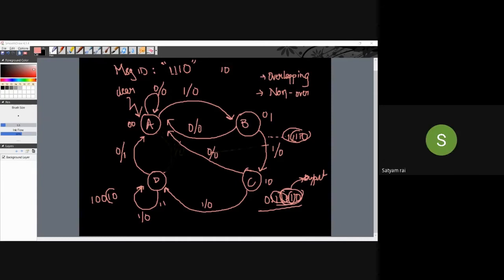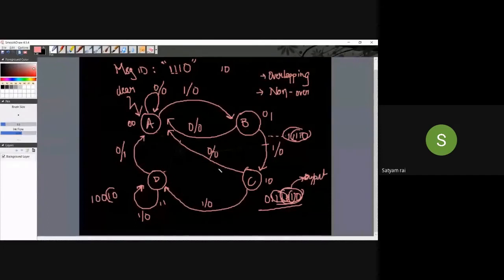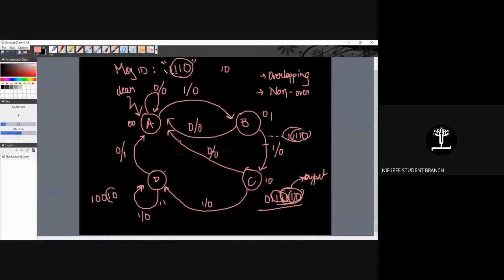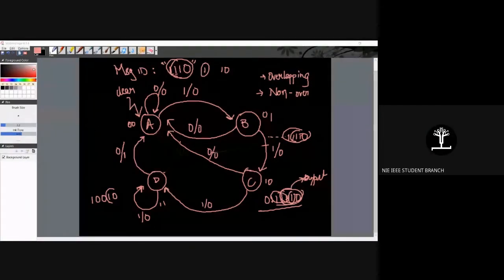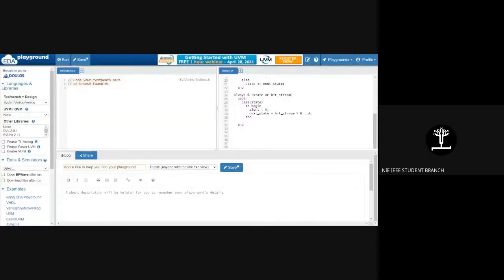So that means when we have an output of 1, the particular device has sent the message. Yes, exactly, this is input/output. Whenever I get the whole sequence 1110, that's when I output a 1, so that I know I've received the whole message sequence. That's what we're building now. So we just finished our case A.